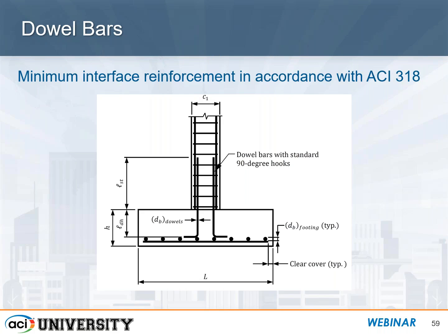You're not going to know about it until probably during construction, where you might find out that the tolerances are not satisfied, and that's when you'd have to go back and check. If, for example, with that beam again, the depth of the beam happens to be a lot shorter than what you designed for, that could have an impact. Maybe it'll work, maybe it won't. So you might have to come up with a remedy based on what you actually find in the field.